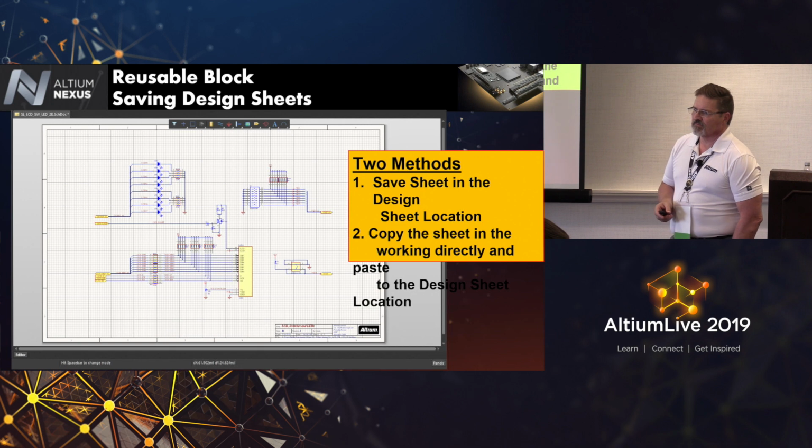That is actually not a good practice in my opinion. I would rather do a component link, which you can access in the PCB document, project component links. Match the schematic instance with the PCB before you do a design transfer. Right. Okay. So component link. Yeah, I understand that. Very good.